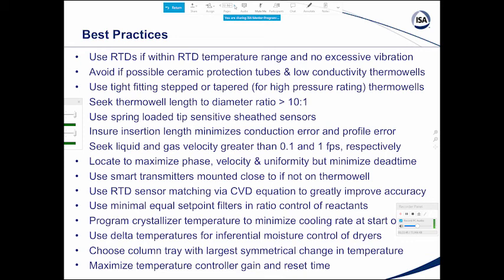So we're talking about very large settings for that, particularly if we're talking about liquid reactors, and if we're talking about columns, oh my gosh, that reset time's got to be huge if we're manipulating, say, the reflux or distillate flow rates. If you're manipulating the vapor rate for temperature control, the boil-up rate, then the reset times are going to be a lot less, because the response to changes in boil-up is so much faster.